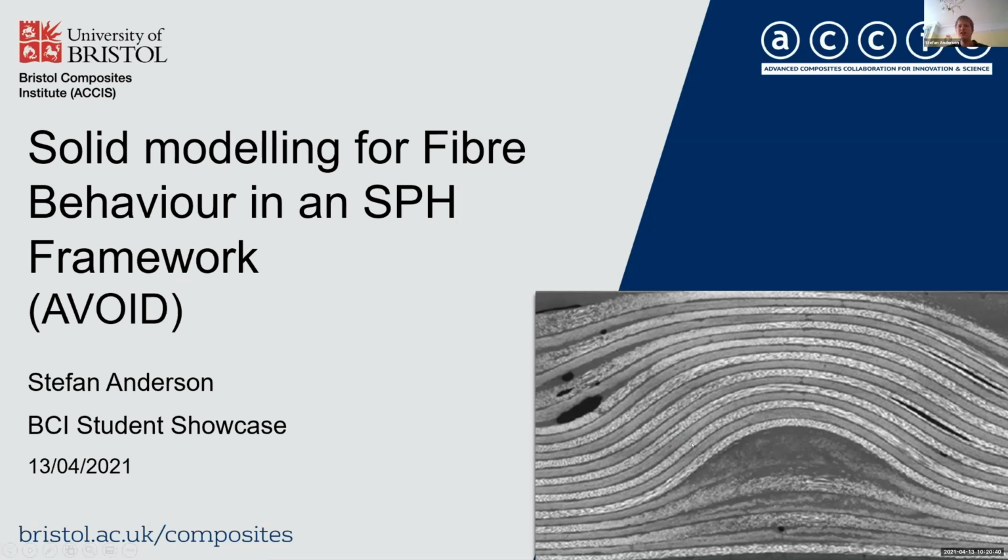You can imagine that to get that up and running, you need a solid model that can handle large deformations, that can handle lots of contact between solid fiber layers, and also interfaces really well with that SPH model. And finally, you need to make sure your process parameters are dead right.